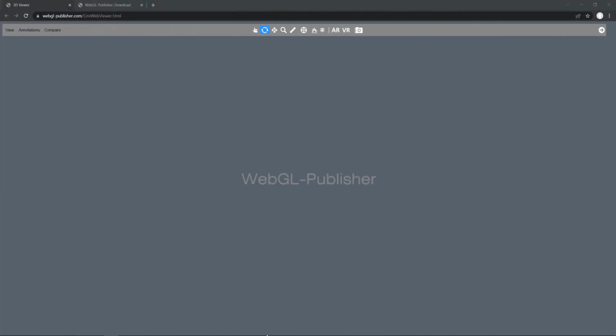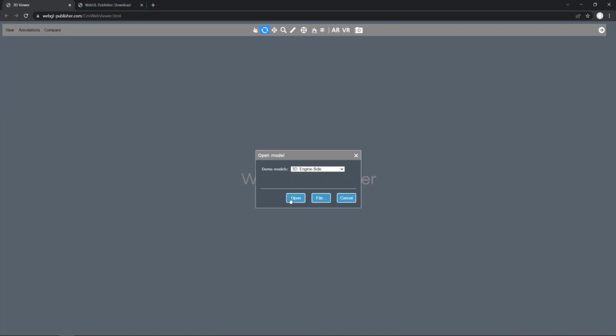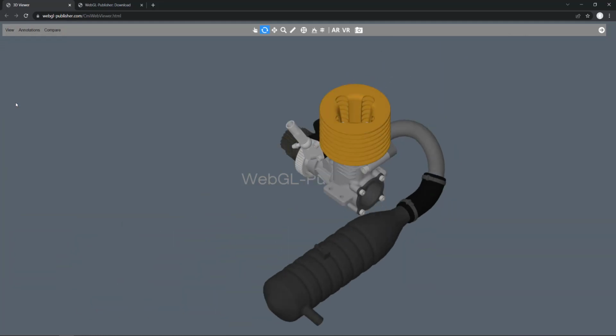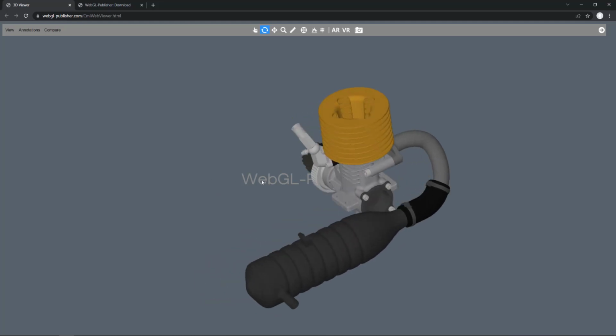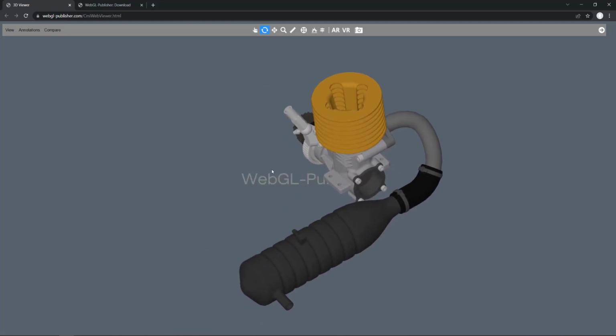To demonstrate the 3D features, I am going to open a 3D model which was converted from Inventor using the JT export. The model shows a multi-level motor assembly and can be viewed by different angles using the mouse. The model can be rotated by pressing the left mouse button, it can be moved by pressing the middle mouse button, and can be zoomed rotating the mouse wheel.